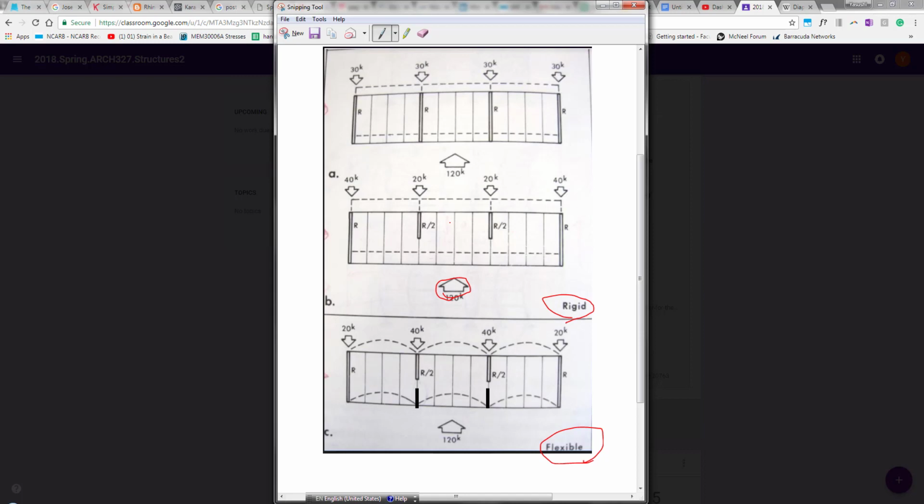I mean, this is plan view, obviously, kind of a roof plan view. So let's say the length of this wall is 1, the length of this wall is half, this one is half, and this one is 1. Because the whole thing tries to move uniformly, the amount of lateral force that gets distributed to each wall depends on the linear length of that wall. So this is linear length 1, half, half, 1. The longer the wall, the more force it can take.